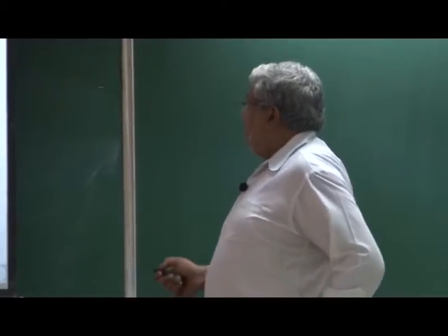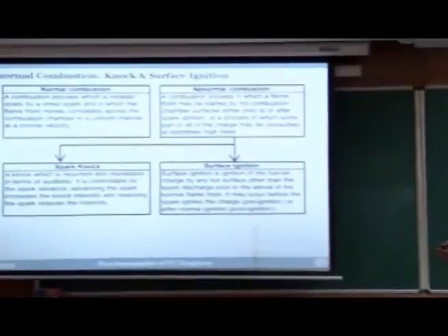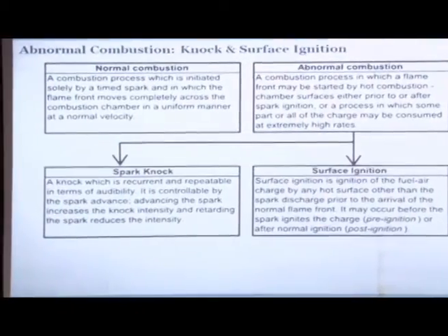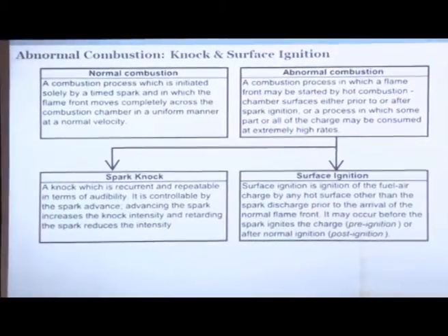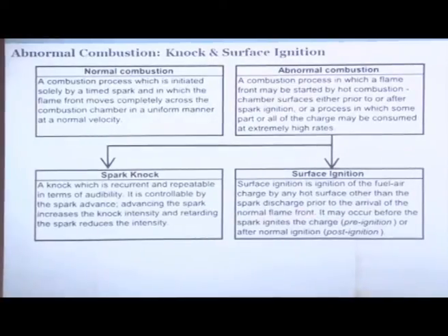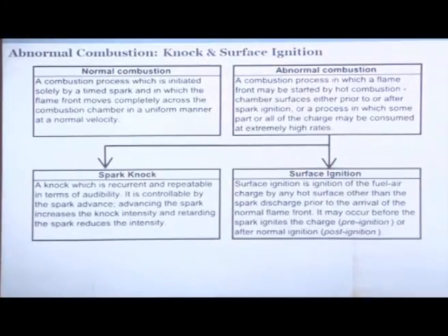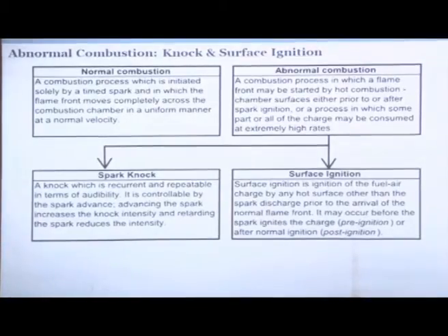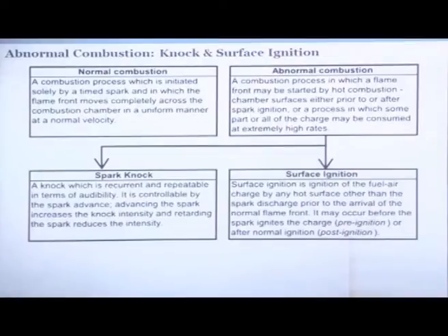Okay. Surface ignition is ignition of the fuel air charge by any hot surface other than the spark discharge prior to the arrival of the normal flame front. It may occur before the spark ignited charge, in that case it is called pre-ignition, or after the normal ignition, which is post ignition. So surface ignition can be before the spark, then it is called pre-ignition, or after the spark, then it is called post ignition.